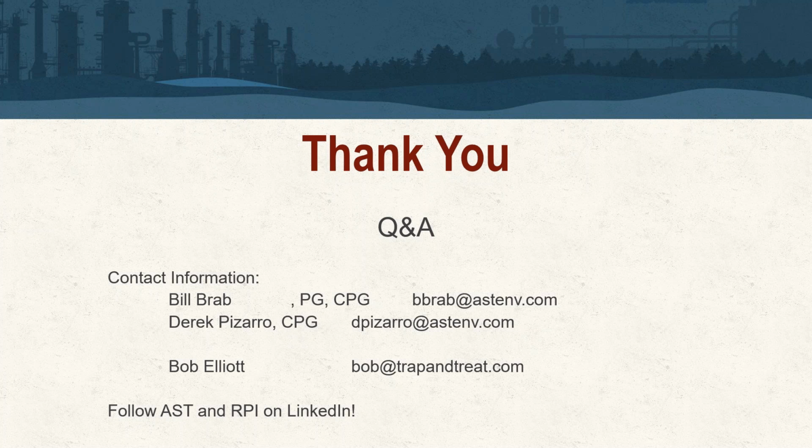So these boreholes are going to have some sort of surface casing that's going to isolate the overburden contribution and protect that bedrock unit for the purpose of preventing any sort of cross-contamination, and then utilizing open boreholes for this purpose. So we're not talking about cased wells with a constructed filter pack here. We're talking about that specific open borehole remaining in place for adding tools later.